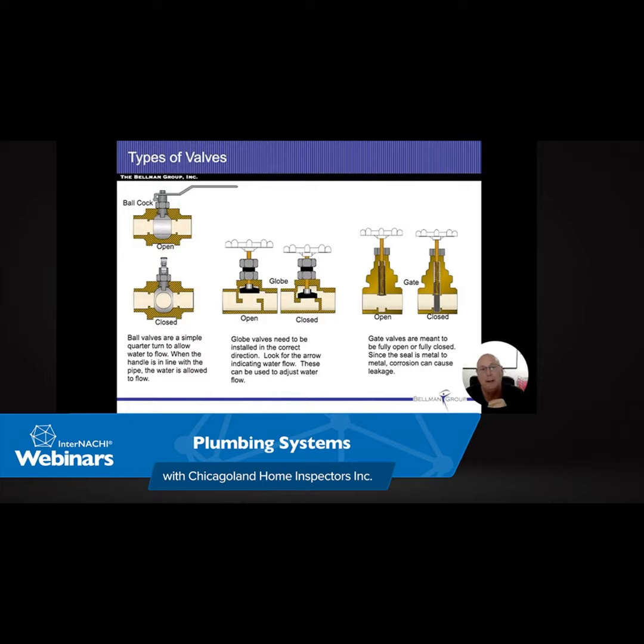Most of this we want to always be water. That scum layer, or the foam layer, that should be less than 2 inches. The sludge layer on the bottom as well, I forgot the exact number on it, but that should be like less than a foot. I think one of our next slides goes ahead and shows that. On some of these pits, we're going to have 2 tanks in them, so they're going to kind of keep the sludge back a little bit longer and just let the effluent pass through. Some of them actually have 3 tanks as well. So here's the slide that I was looking for. 24 inches is what we want to keep it under, and we're not going to know that.